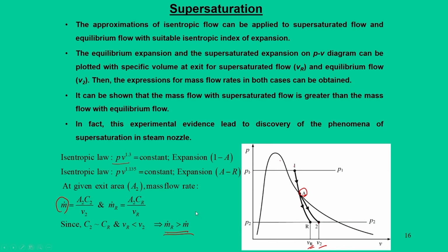Basically, why are we discussing this phenomenon? The concept was not known, but in reality when the mass flow rate was measured, people tried to understand why this mass flow rate is higher than the mass flow rate in the conventional or equilibrium flow case. Then many theories were developed and the concept of supersaturation was framed. So, the experimental evidence from the mass flow rate led to the discovery of the phenomenon of supersaturation in steam nozzles.